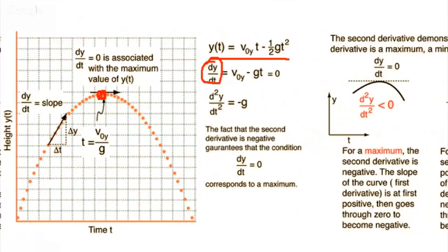Same technique you use in your perturb and observe method. There also I'll be telling you that method. So that is a calculus method. You are finding the slope. When the slope is 0, you understood that you have reached a maximum. But how will you understand whether you have reached a maximum or a minimum? Because when the slope is 0, you would sometimes have reached the minimum also.